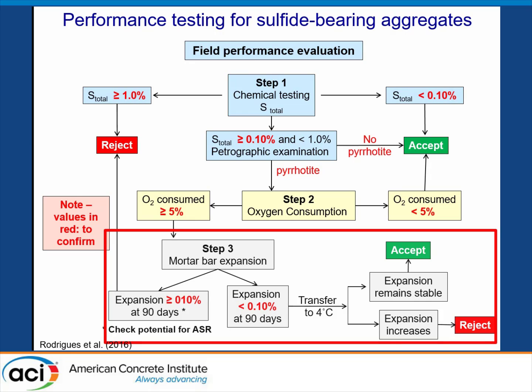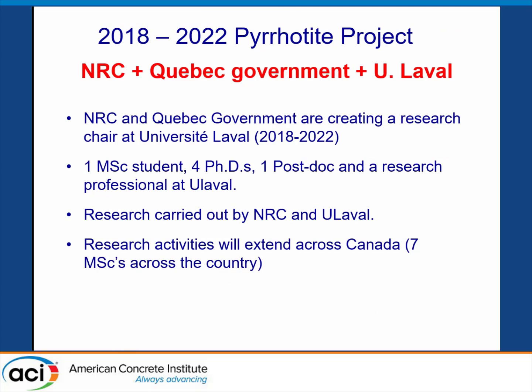increase in the first part of the test, because we had aggregate with both problems. They were alkali-silica reactive and they were sulfide-bearing aggregate too. But in the first step, it's really good for ASR too. But if it's just ASR, the expansion will be high after the first step, but won't continue after that. They will have a plateau after that. But we need to try more to separate both types of mechanisms.